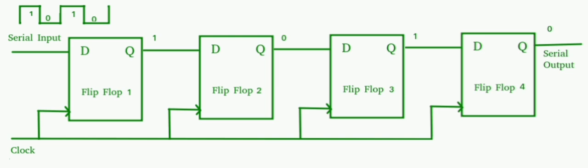The on-off switches S0, S1, S2, S3 are at the same potential. You always consider the bit where the input reference voltage is supplied as the MSB. The bit stream B3, B2, B1, B0 in base 2 has MSB equal to B3 and LSB equal to B0.